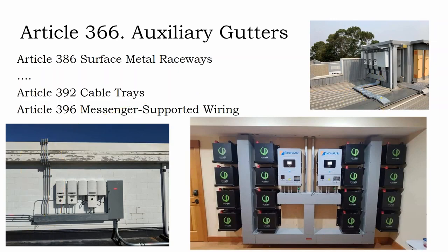So what the gutters do is allow you to simplify all of this stuff. We have 8 different circuits, or 8 different conduits that might contain 2 or 3 circuits in them, landing inside here. And each of these circuits needs to get divided between multiple inverters, and then also come out and go into a broader box before we get back to our main point of interconnection.